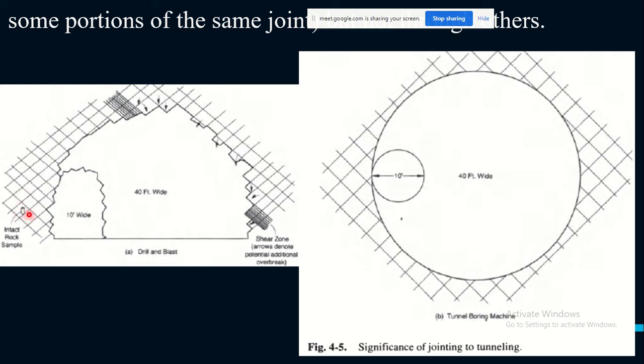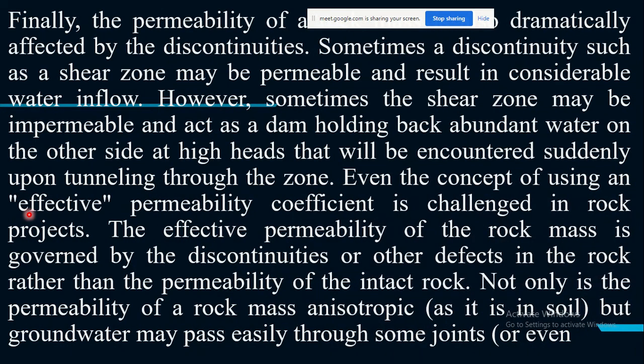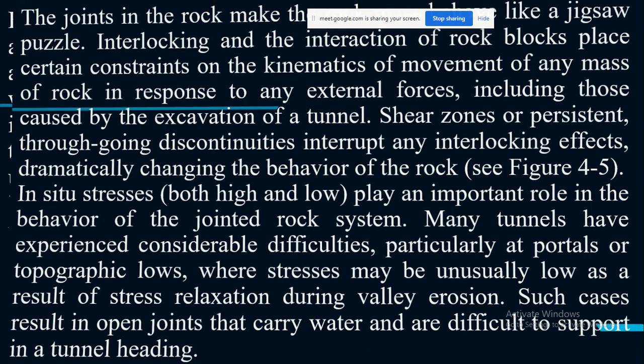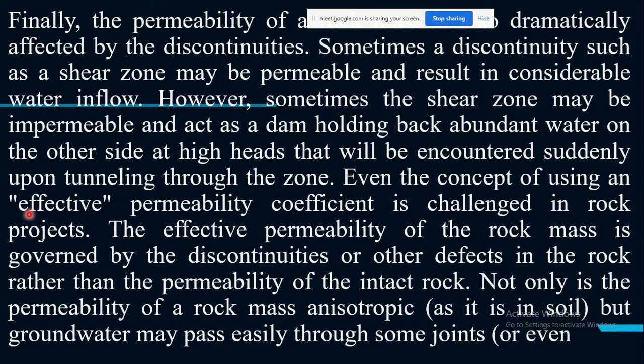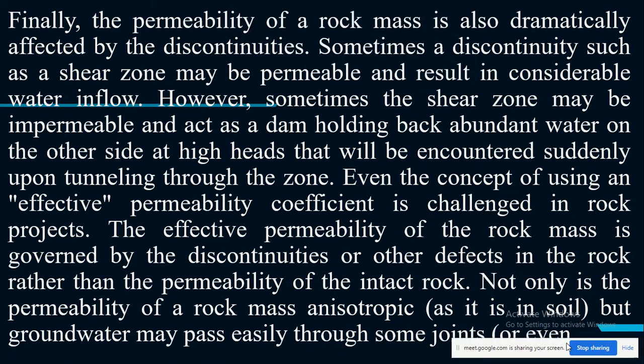So this is why we are saying the behavior of the tested rock in the lab should be taken only as an upper bound, rather than the actual. The actual behavior is more influenced by anisotropy on joints, and the values obtained from the lab have to be modified to be applied in situ.